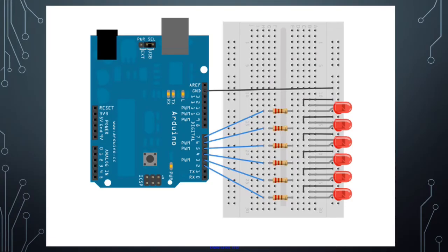Here's how we would connect multiple LEDs, and I want to review this specifically because it is part of your lab. This really applies to any component, but LEDs are a nice simple component for us to use. It's essentially the same principle as connecting one LED, just duplicated. But there's some nuances that I want to cover to make sure you're not running a bunch of extra wires, to hopefully help you out. So you'll see we have our black wire running from ground to our ground line on the breadboard, right? So now everything in this column will be grounded.